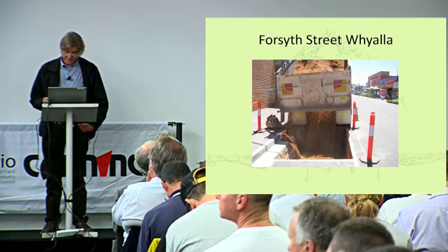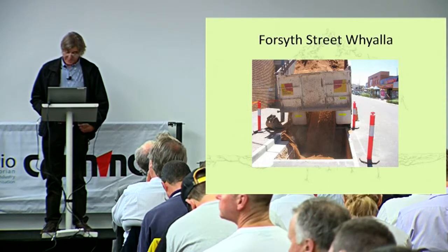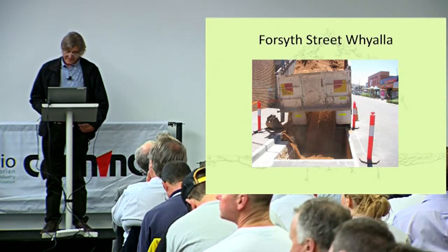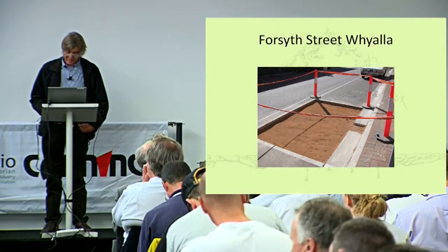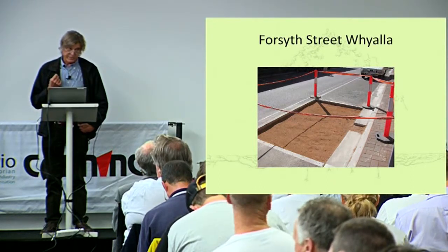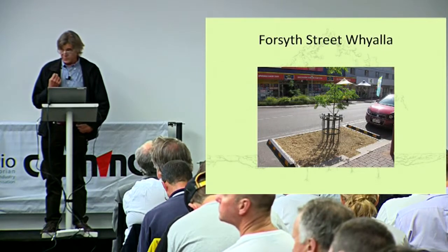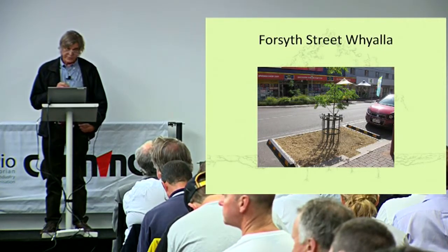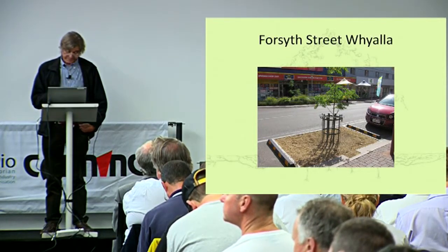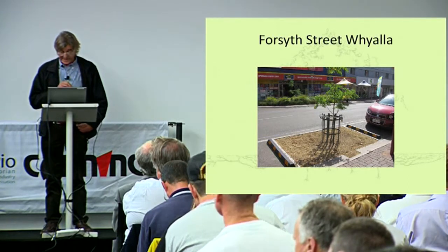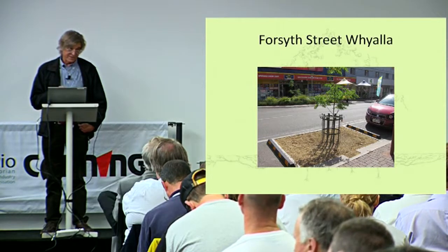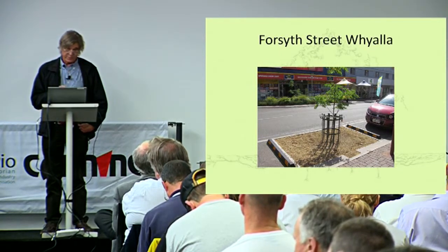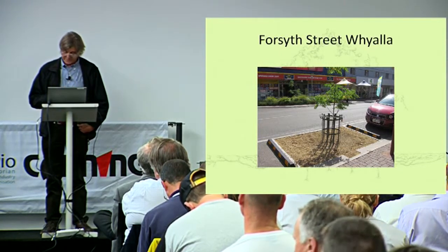Just installing good quality loam into that space, and then covering all that up with some sort of gravel surface, so the water can actually infiltrate from the water table into the tree pit. And they're very sandy soils at Whyalla, so there wasn't a concern with the tree root zones becoming waterlogged.